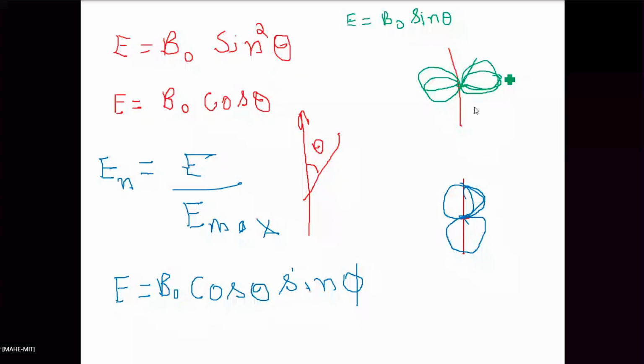Okay, so that is called theta HP, theta half power. If you are getting confused, please let me know and I will clarify it. So theta HP is the direction of half the maximum radiation, the half power point. How do you get that?